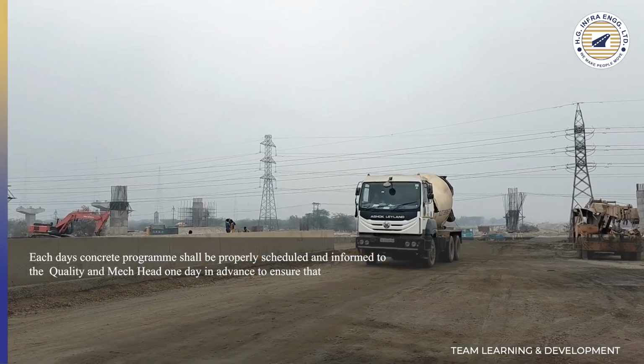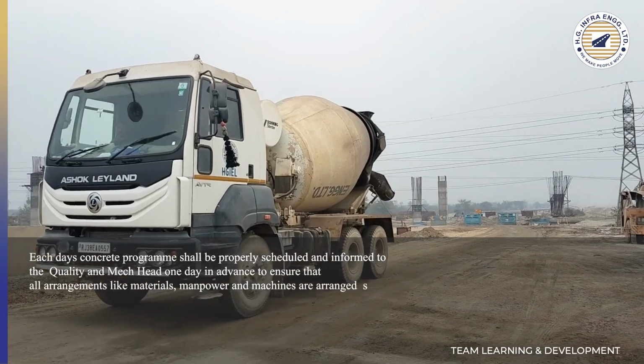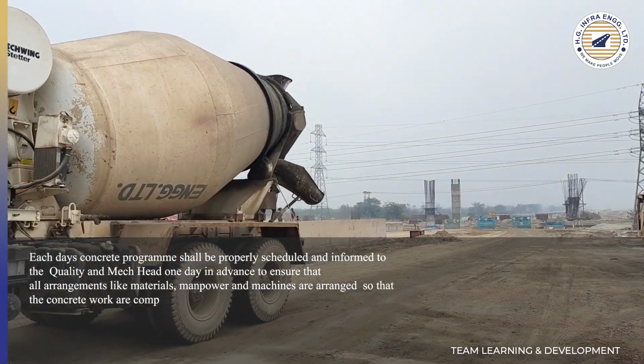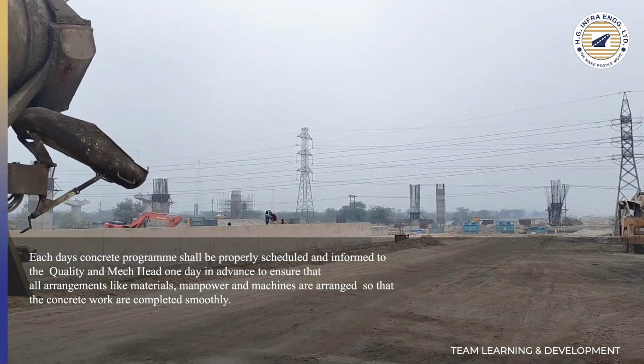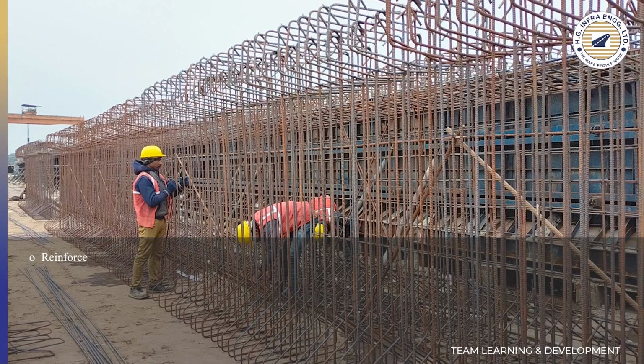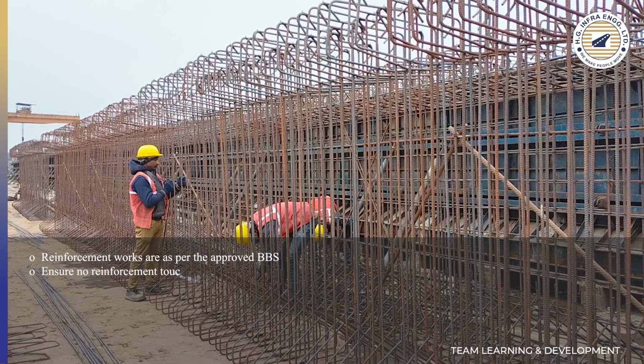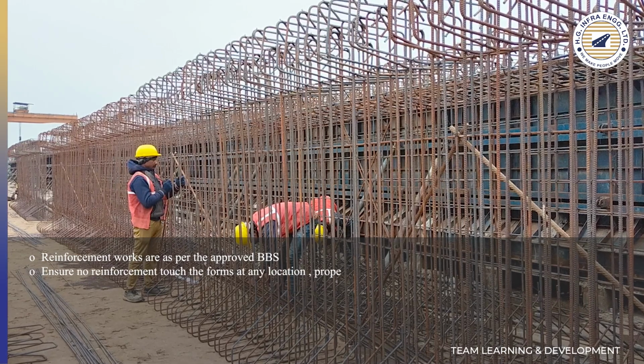This is to ensure that all the arrangements like materials, manpower, and machines are arranged so that the concrete works are completed quickly. Pre-concreting requirements. First, reinforcement works are as per approved BBS. In short, no reinforcement touches the forms at any location.